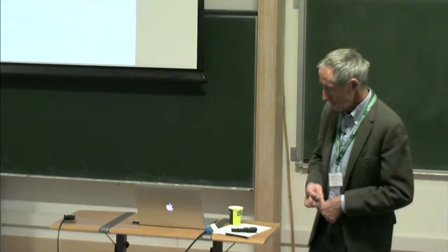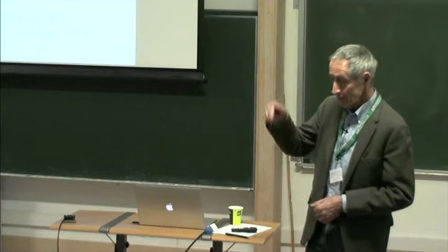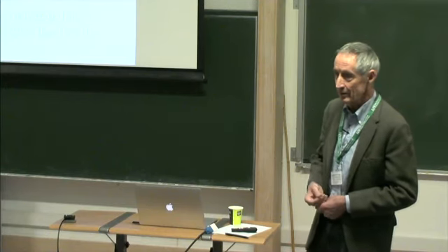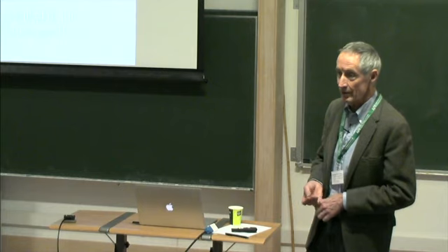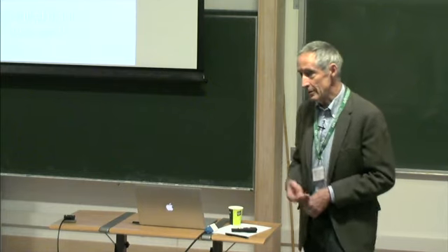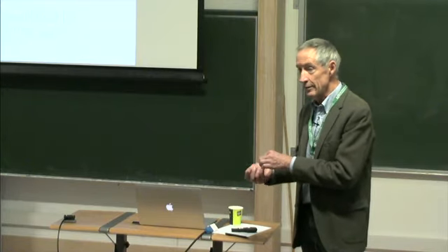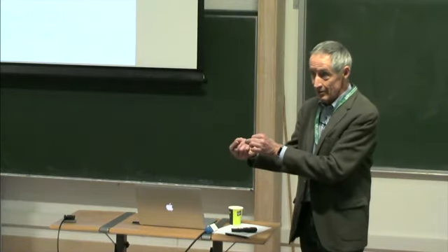It's not hard, obviously, to rig up a point bending test. I've done that, and I've used it to try to correlate the effective bending strength with my input value, which is the tensile strength at the connection.